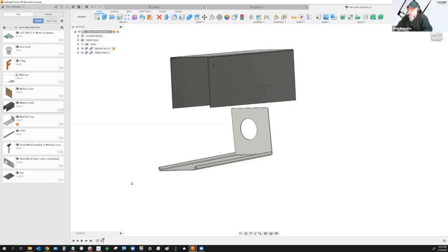If I put a screw into a hole, that screw is not rotating. There's 0 degrees of freedom there. So I would put the screw in the hole with a rigid joint so that if that part moves around, it takes the screw with it, as if they're glued together, or the screw is actually just wedged in there and there's compressive forces on those threads that keep it in place. Does that help, George?